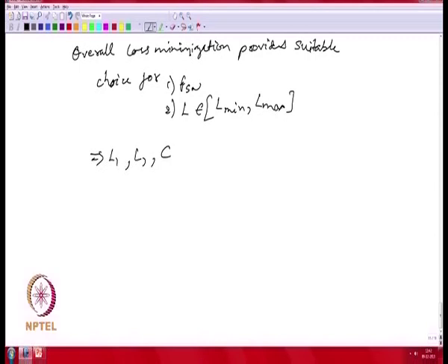non-idealities of your power converter, and a primary non-ideality which you automatically get once you go into a higher order filter design is how to deal with filter resonances. So, this is one aspect that we would need to consider.